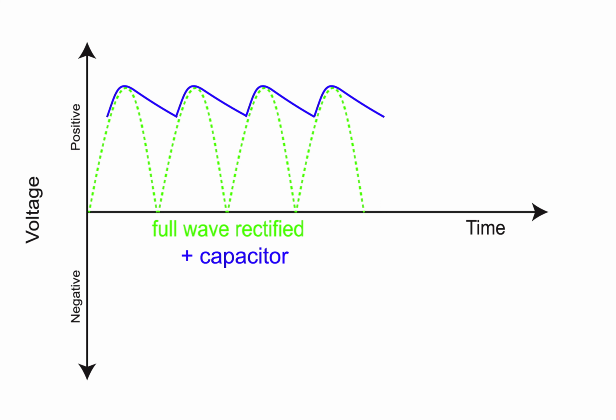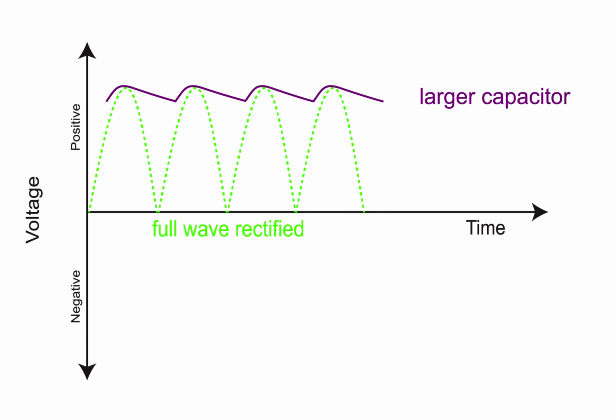The capacitor is typically quite large and creates a reservoir of energy that is supplied to the load when the rectified voltage drops. The incoming energy is stored in the capacitor on the rising edge and expended when the voltage falls. This significantly reduces the amount of voltage droop and smooths out the voltage. Increasing the storage capacity of the capacitor generally produces a higher quality power supply.